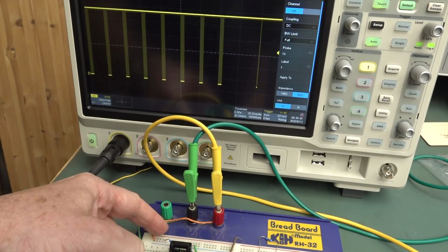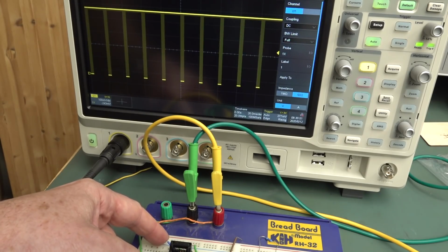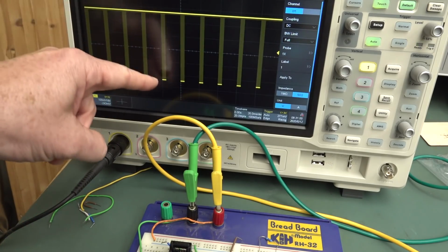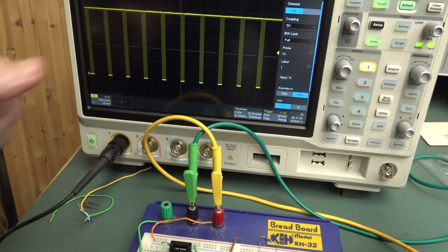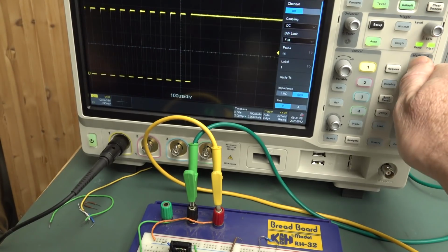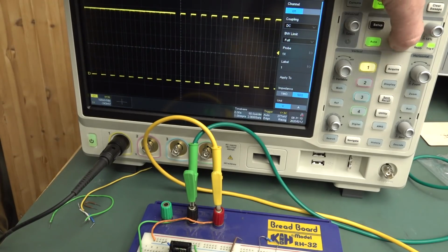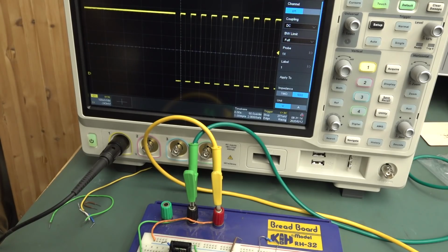Let me touch that. Yeah, look at that. I can change that just by touching that input. Wow. And by the way, this is 0 to 5 volts. These are real, genuine totem pole driven, hard outputs. This micro's not mucking around. It's actually genuinely driving those output signals hard. So it's not just the output flapping around in the breeze.